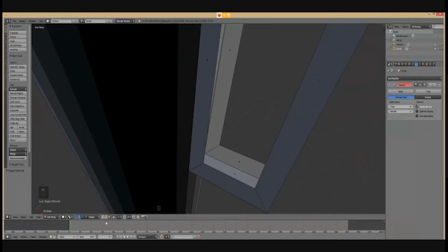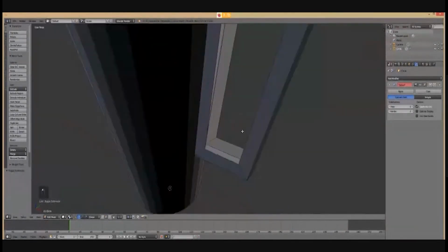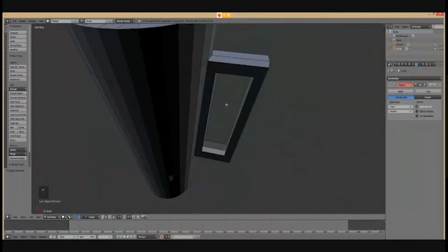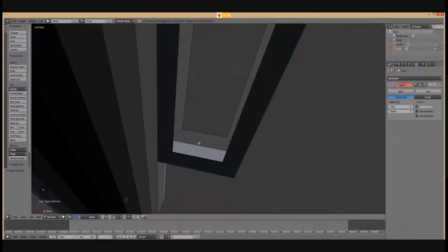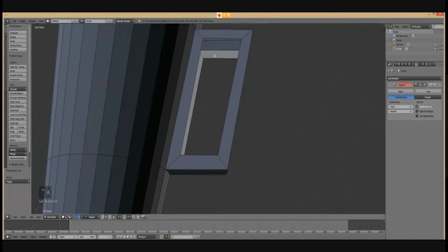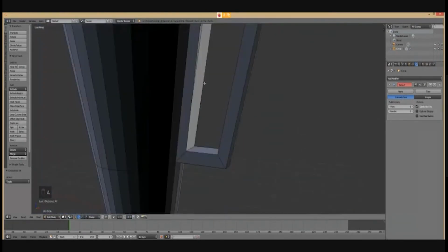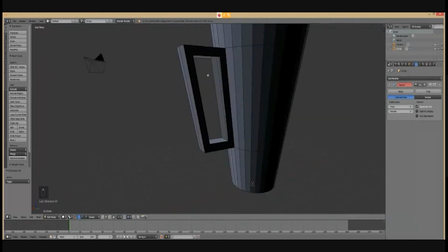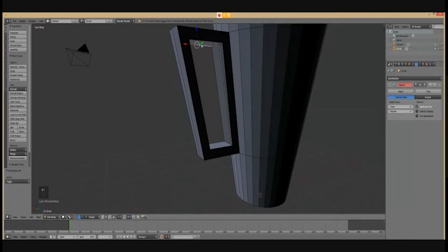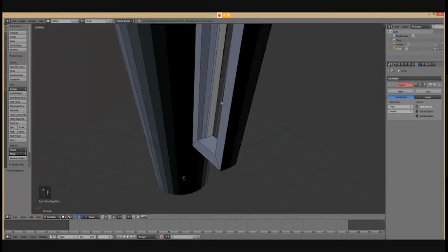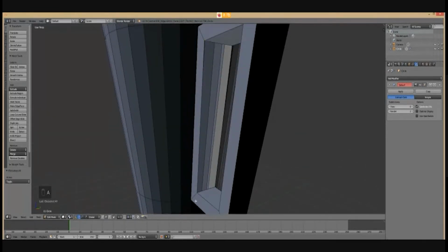So I'm going to go to my edge select, and then I'm going to basically begin to add faces over here. So I'm going to choose this edge first. Holding shift, I'll select this edge, and then I'll press F, right? So the face is formed. Similarly, I'll repeat the same thing over here for the top. Okay, so select that, holding shift, select that, click on F, you've got a face, right? Now, to apply the faces over here, hold shift and cover the entire boundary.